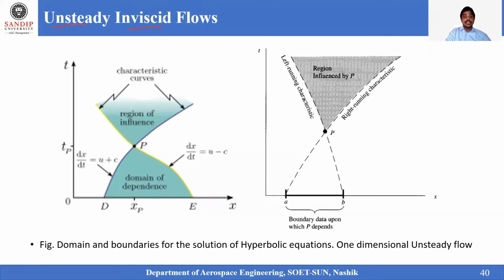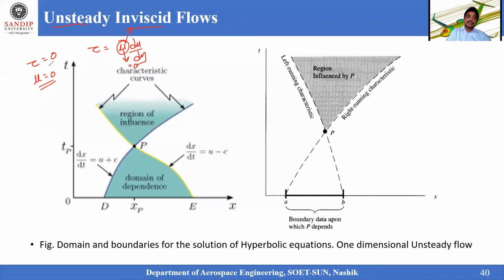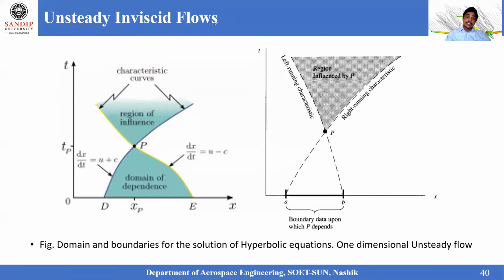Here we are dealing with unsteady, and at the same time, in the second case, with inviscid fluid flow cases. So that means μ is equal to 0. Where viscosity is not available, from Newton's law, that is μ du/dy, defined along only one axis, the inviscid case states that μ is going to 0. When μ is going to 0, the shear stress available is going to be 0. So we are assuming the complete fluid flow as unsteady and inviscid.